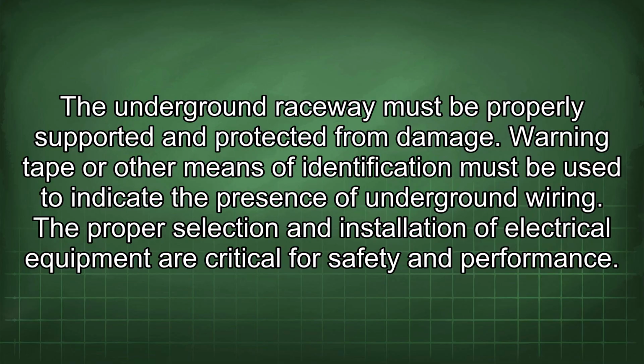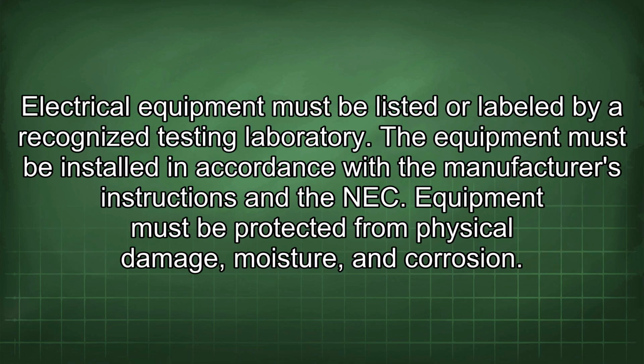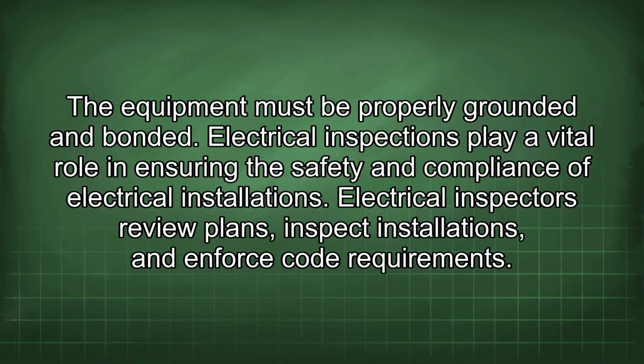The proper selection and installation of electrical equipment are critical for safety and performance. Electrical equipment must be listed or labeled by a recognized testing laboratory. The equipment must be installed in accordance with the manufacturer's instructions and the NEC. Equipment must be protected from physical damage, moisture, and corrosion. The equipment must be properly grounded and bonded.